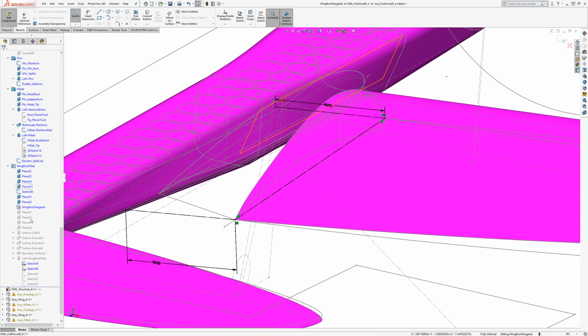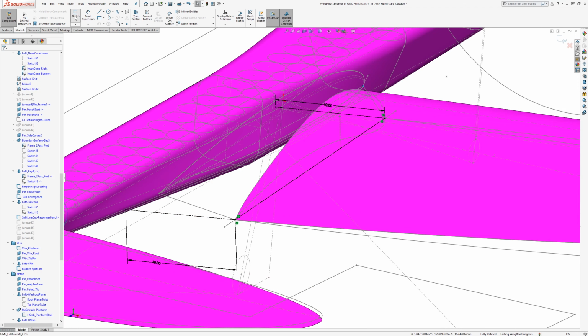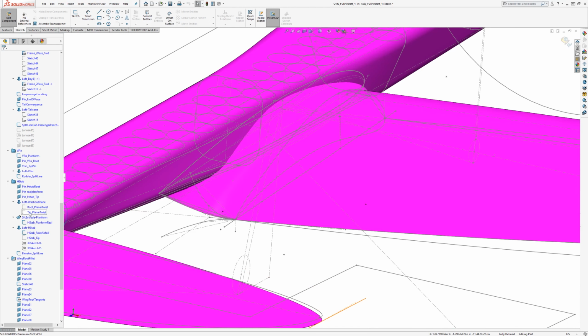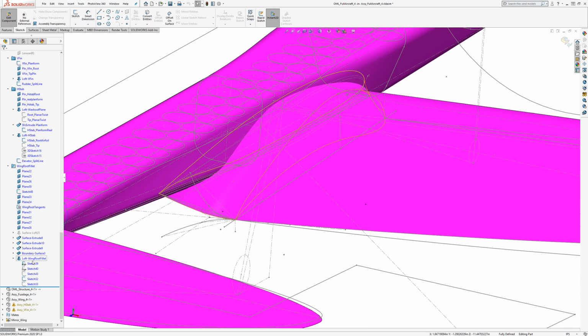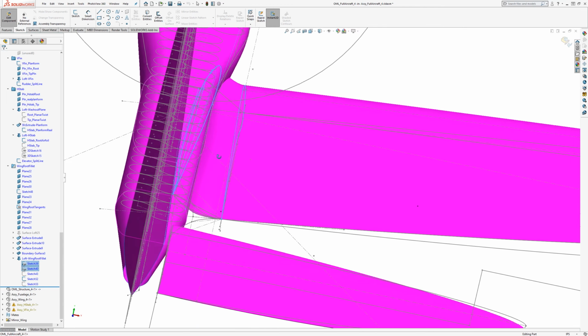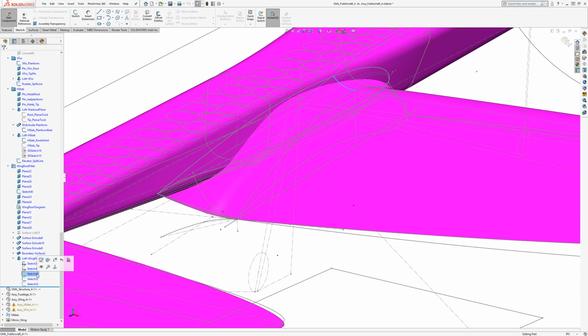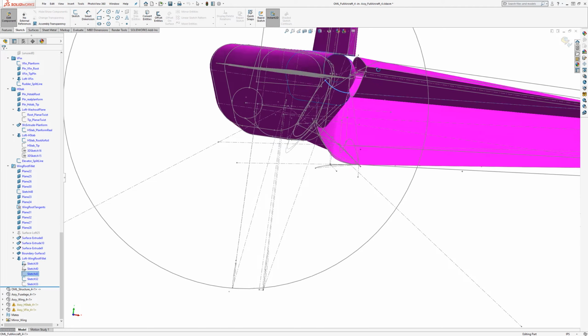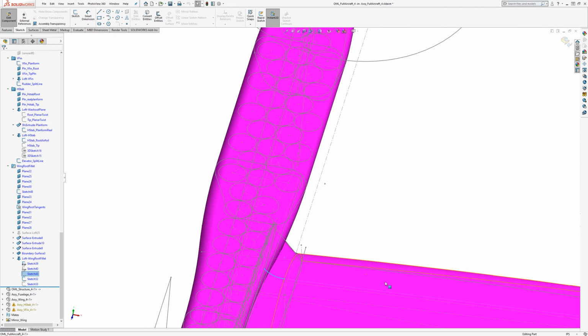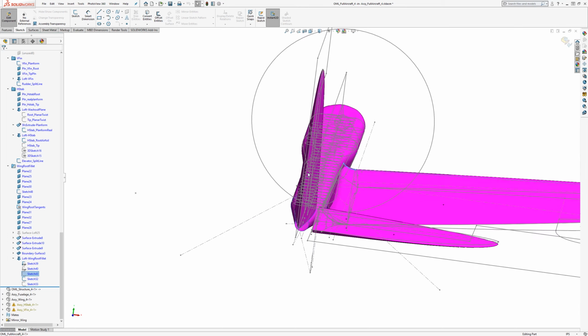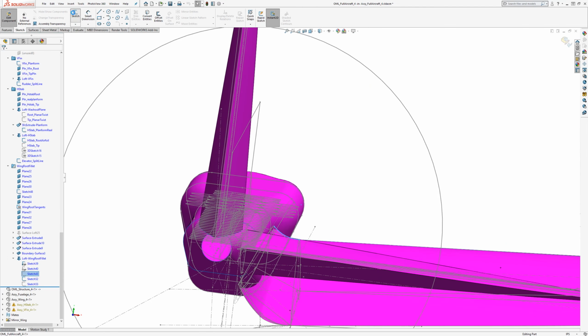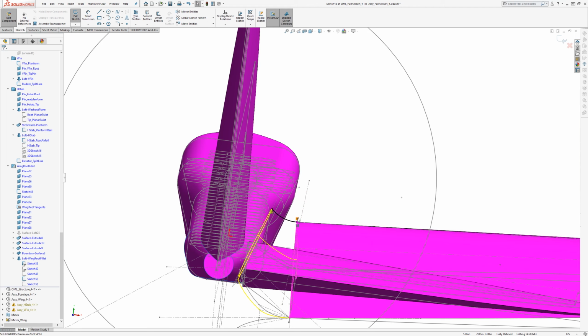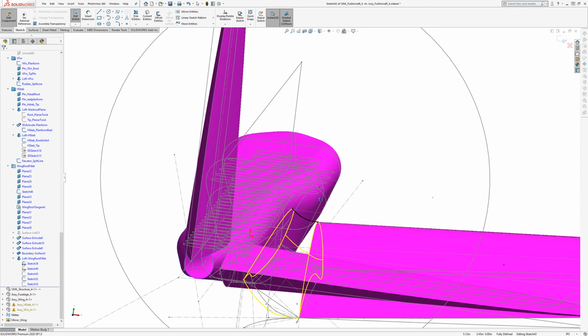And so what I did there, get out of the 3D sketch, is, there's a loft from that flat-ish airfoil to the root airfoil, and it's guided by one sketch along the right plane with some pierced points on either airfoil.